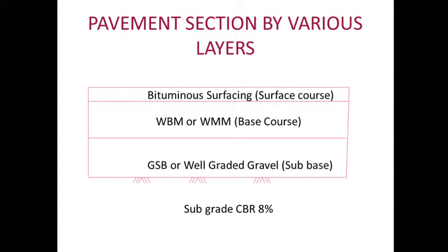Normally, the subbase in India is granular subbase or well-graded gravel, whereas the base course is waterbound macadam or wet mix macadam, and the surface course has bituminous surfacing, maybe bituminous concrete or dense bituminous concrete or bituminous macadam or dense bituminous macadam.